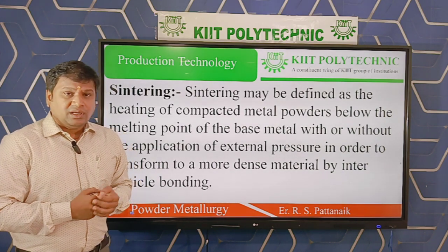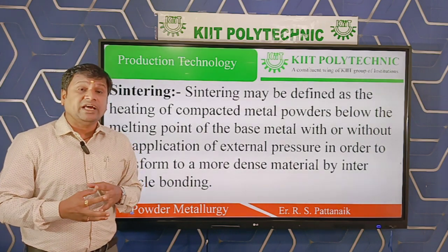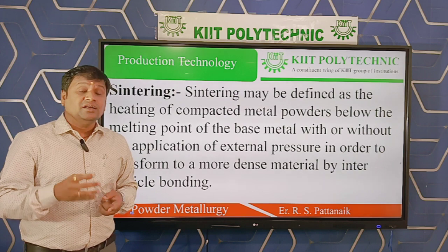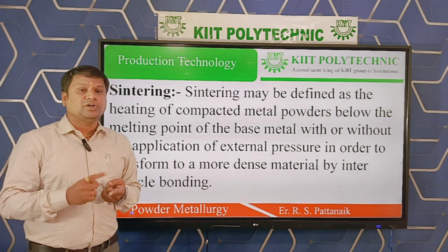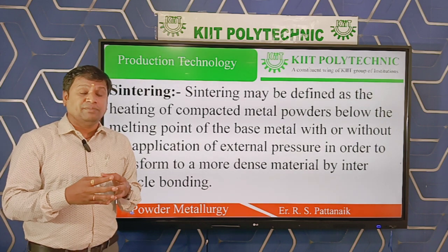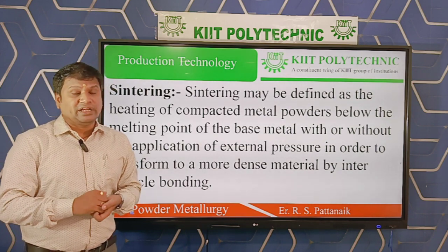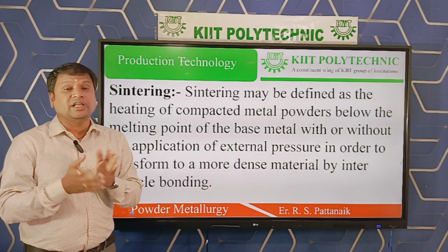Once again, in this process the compacted metal powders are heated below the temperature of the base metal, not to melt it, but to bond the metal powders by interparticle bonding into a final product.